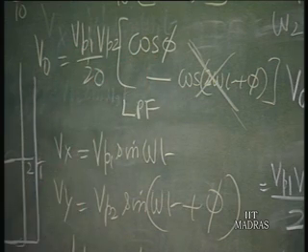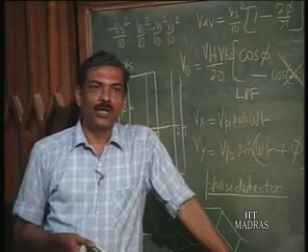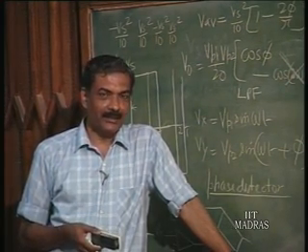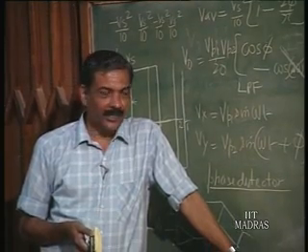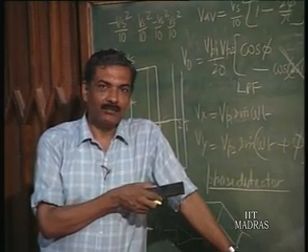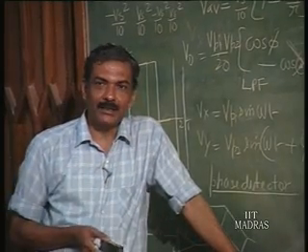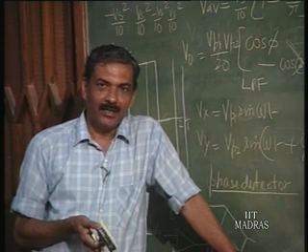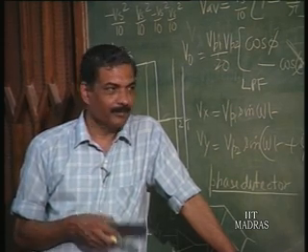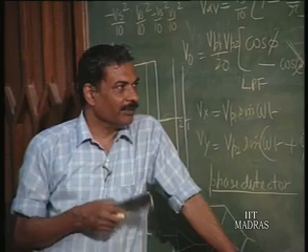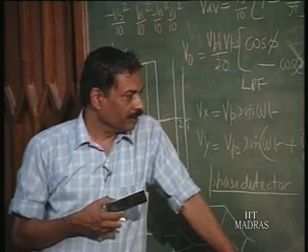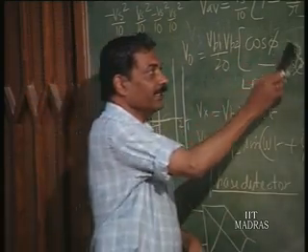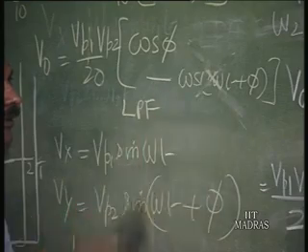You can use this information as a direct replacement of what is called the 2 wattmeter method of power measurement. The 2 wattmeter method of power measurement in a 3-phase circuit can be translated in terms of 2 such multipliers being used, in order to evaluate the power of the 3-phase circuit. So, it can be used as a wattmeter. Phase detector, wattmeter.